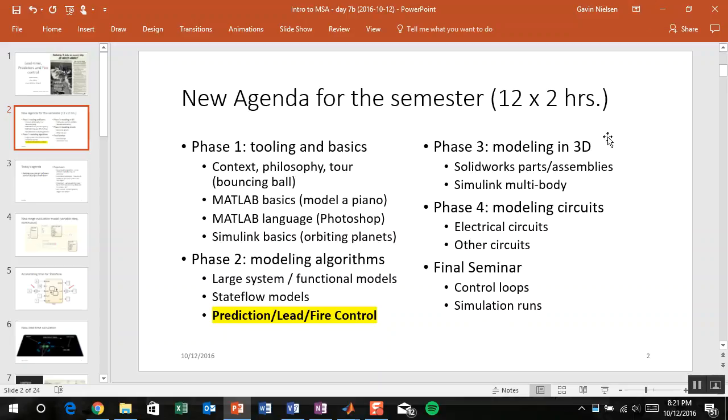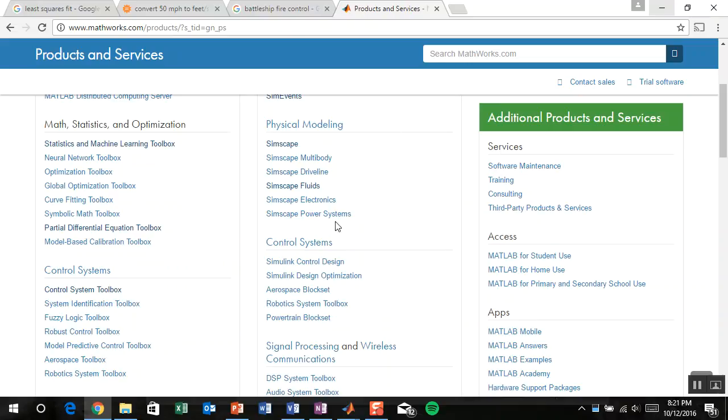But where we're going is with these physical modeling tools, and there's a bunch of them: Simscape, multibody, and driveline. We're going to be using fluids and multibody. Suddenly the software cares, and it's really specific, to the extent of asking whether you're talking about gallons or liters. Which is really great, because now you can say exactly what you're talking about. This hydraulic motor has a 90 cc displacement, or I want this flow rate to be 90% efficient at 20 gallons per minute.